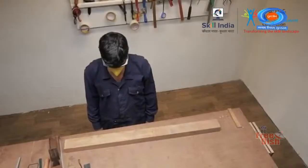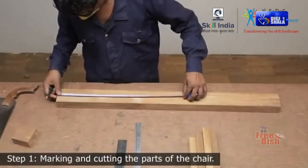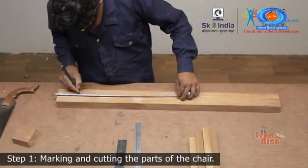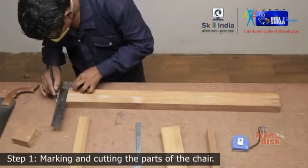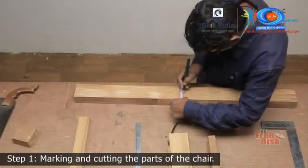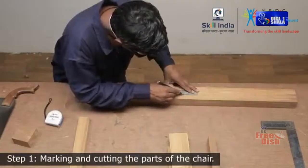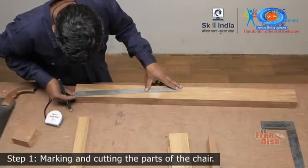All the measurements must be taken from either face side or face edge. Measure and mark the points on the back leg for the tapering bend on the backrest. Use a steel ruler and pencil to draw taper lines from both the width points.